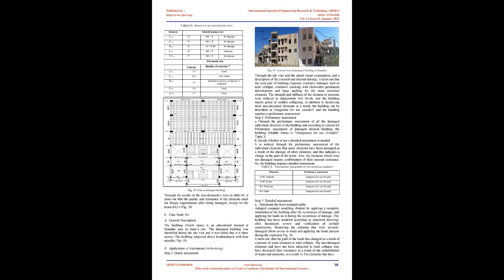B. Assessment of residual strength for existing elements. Non-destructive tests were conducted for samples of structural elements whose severity was evaluated as slight and none, and some of the elements whose severity was moderate to heavy. Table 9. Through the results of the non-destructive tests in Table 10, it turns out that the quality and resistance of the elements meet the design requirements after being damaged, except for the beam B12-6, Fig 18.